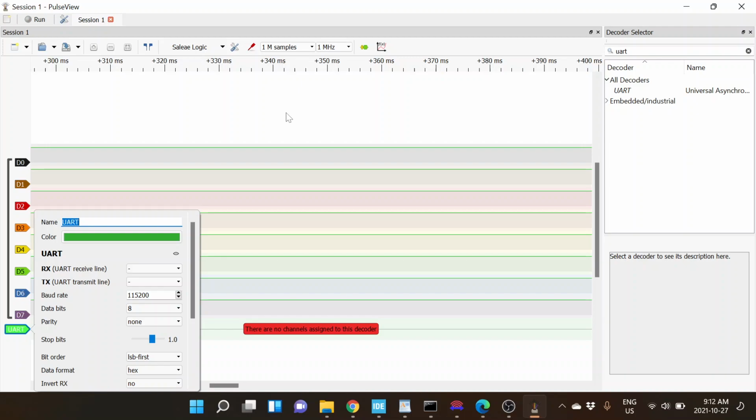Again, you're going to see a mark level. We go down to a start bit, then the least significant bit, all the way through, typically 8 data bits. The other thing that it will ask for is usually parity or no parity. If we send ASCII, that's 7 bits, so your 8th bit can be a parity, and you can check whether it's even or odd parity. Typically, it's sent no parity. Your choice is 1, 1.5, or 2 stop bits, and then it goes into a mark level for your transmission.